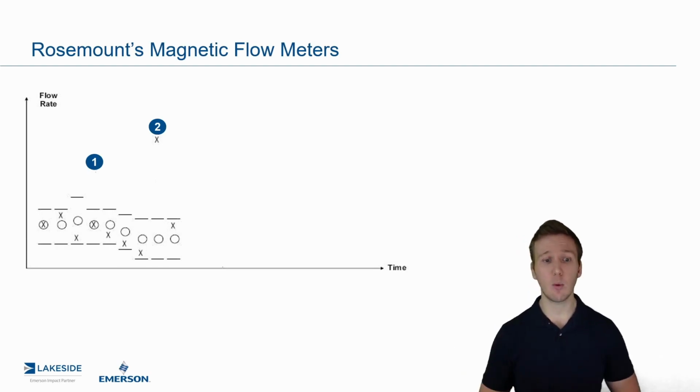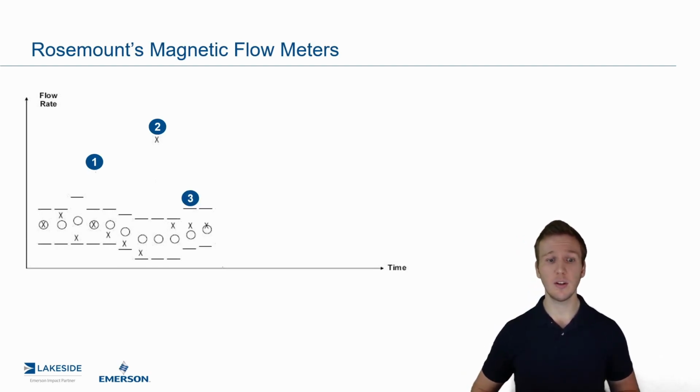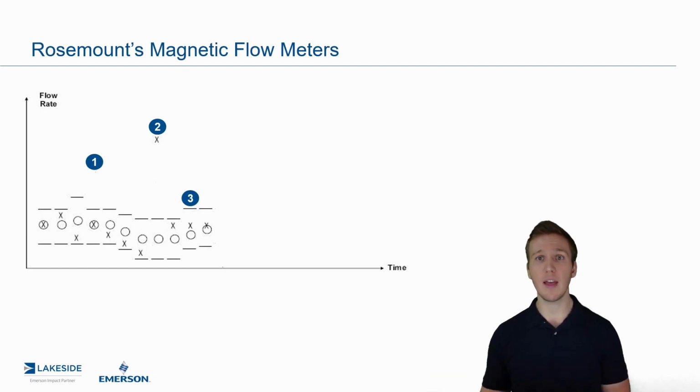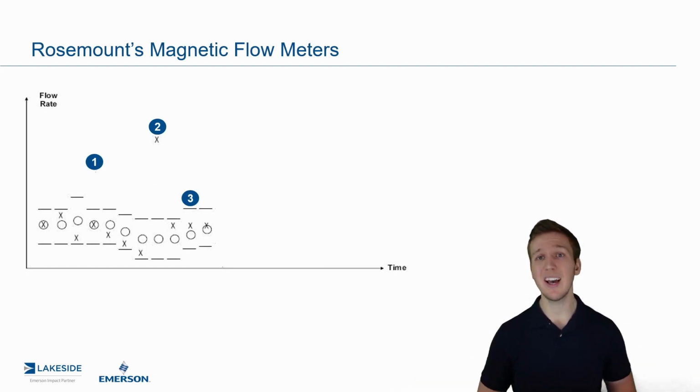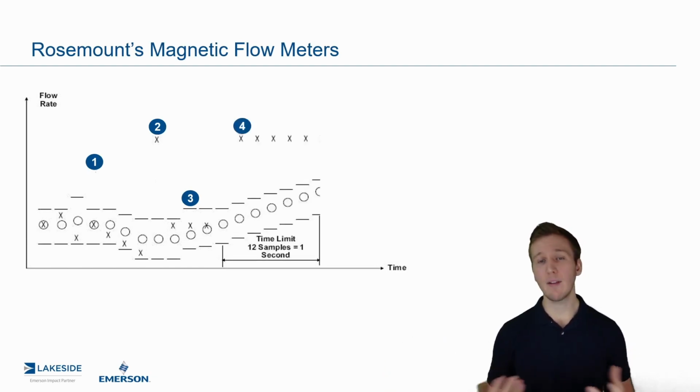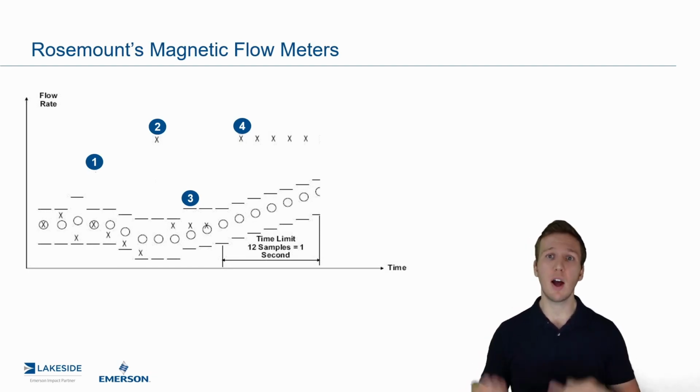As you can see, the next point is within the threshold, and points 3 and 4 beyond that are within that threshold. So point 2 is just ignored as spike noise, not included in the average. As a result, we have a consistent, stable measurement that, again, we can still control off of. Now point 4 comes along, and similar to point 3, we look at it, we acknowledge it, we do not include it in the average, we wait for another data point.